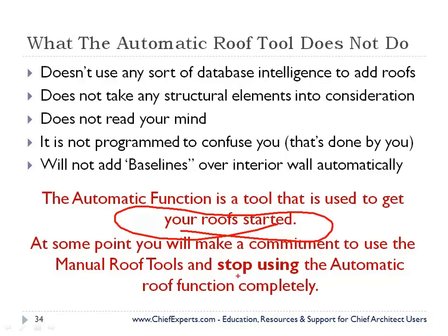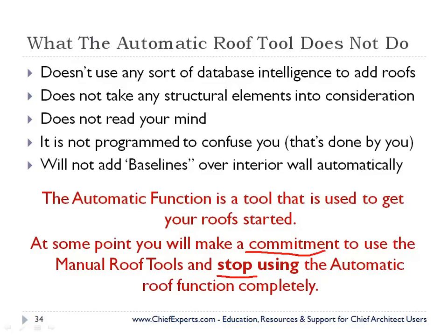Again, some plans it's going to do pretty good. It's going to get most of the roof in for you. At some point, you must make a commitment to stop using the automatic roof tool function and do everything manually. Because if you've done some roofs manually and then you change from manual and redo them automatically, you're going to lose all your changes. Even though Chief has some buttons there that say, well, retain these roofs, retain it. Doesn't matter. We don't use those.